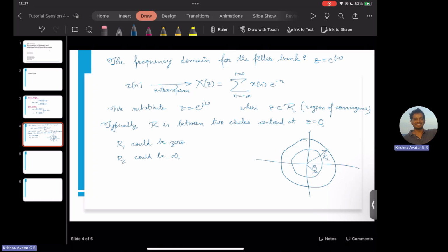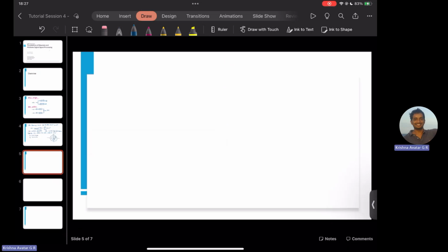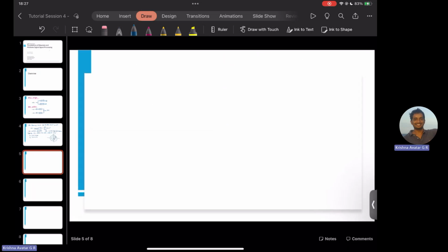And say if we have this Z transform of a sequence, then it implies that the sequence will have a discrete time Fourier transform. Essentially, this part of substituting Z equal to e to the power j omega is bringing our Z transform and converting it into what we call the discrete time Fourier transform of the sequence. Now, suppose we were talking about these classes of analysis filters, right? So there are two classes of analysis filters.